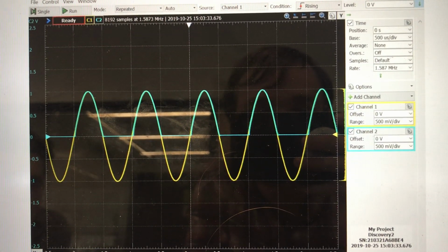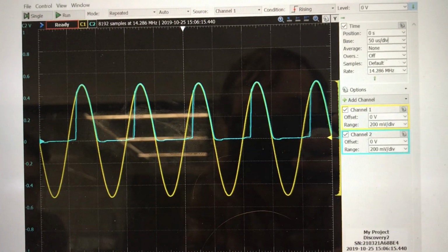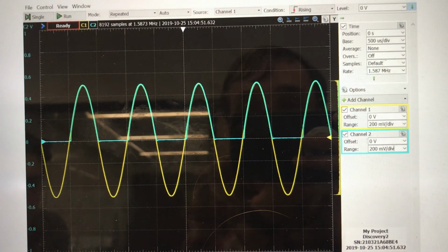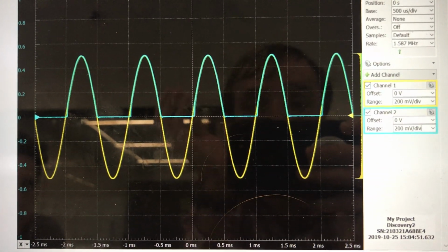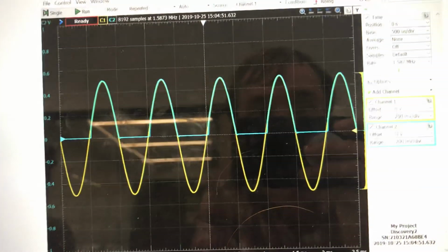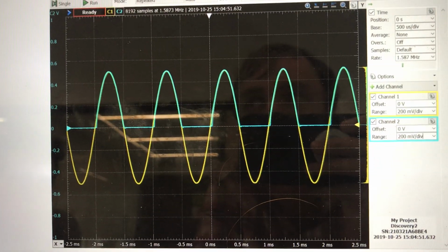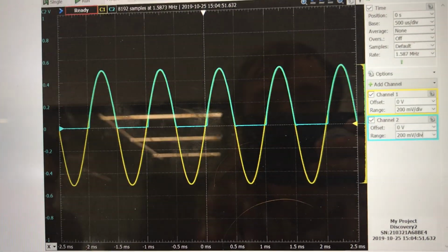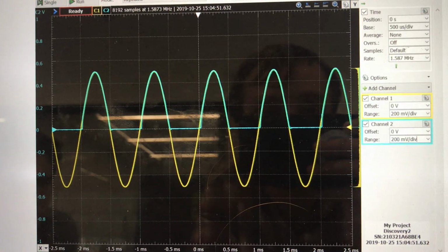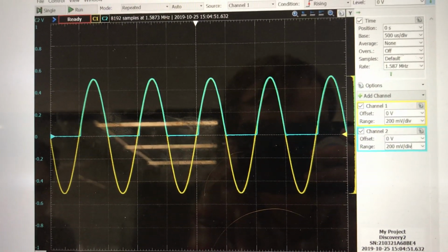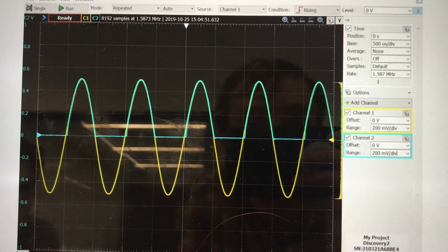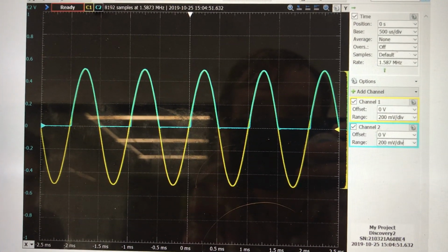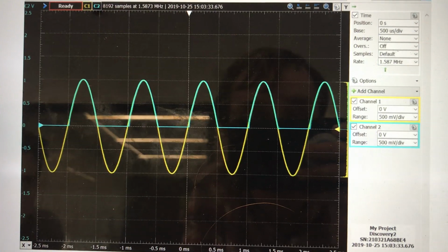We have no voltage drop, only half-wave rectification, and we can even decrease it to 0.5 volts amplitude, 1 volt peak to peak. Before, we wouldn't have had any output for this with the passive circuit, because the input has to be above around 0.6 or 0.7 volts. But here the output still matches perfectly because it's active. These two were at 1 kilohertz.